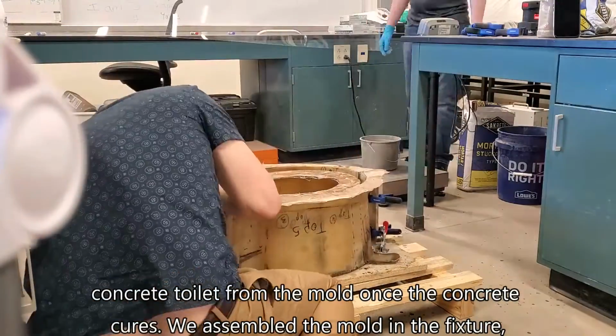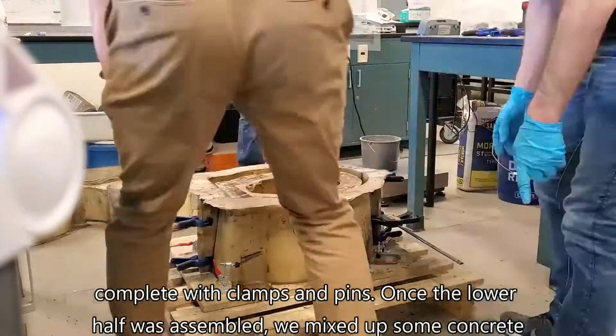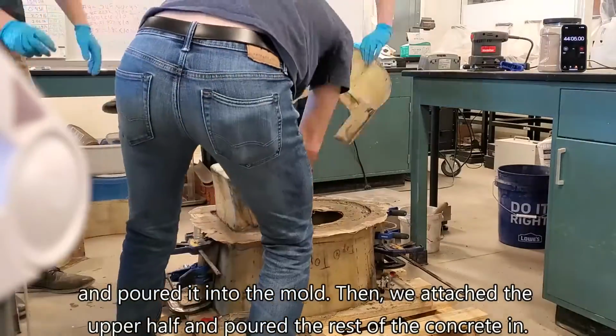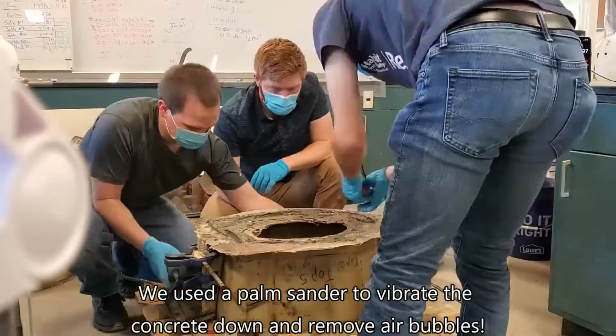We assembled the mold in the fixture, complete with clamps and pins. Once the lower half was assembled, we mixed up some concrete and poured it into the mold. Then we attached the upper half and poured the rest of the concrete in. We used a palm sander to vibrate the concrete down and remove air bubbles.